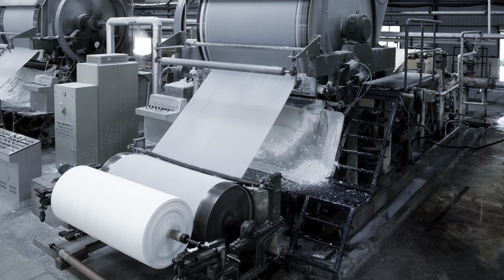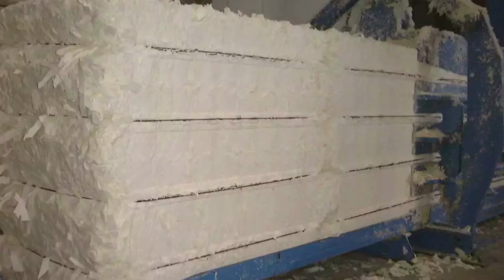In the pulp and paper industry, the most important applications of enzymes are: present-day bleaching of kraft pulp uses large amounts of chlorine and chlorine chemicals whose byproducts are toxic, mutagenic, persistent, and bioaccumulating and cause numerous harmful disturbances in biological systems. Enzymes provide a very simple and cost-effective way to reduce the use of chlorine, chlorine compounds, and other bleaching chemicals. For example, in the pre-bleaching of kraft pulp, xylanase enzymes have been found to be most effective for this purpose.